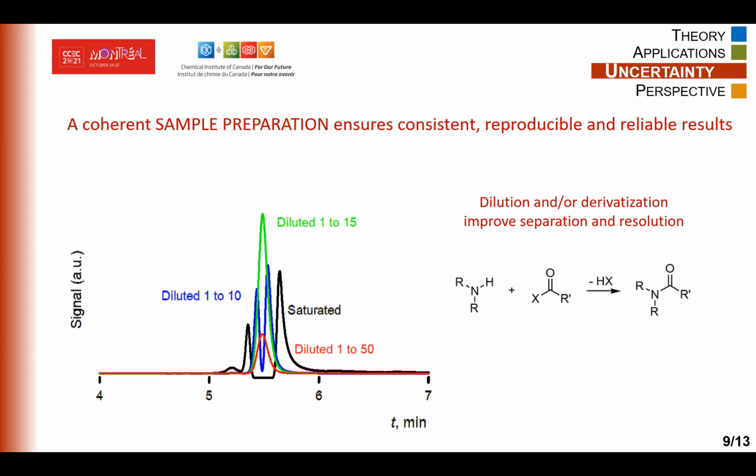They normally select the wrong filter. There are several membranes available, and they all have different applications. For example, in your lab, I'm sure you have cellulose acetate syringe filters, and they're very common, cheap, and used for aqueous solutions and biological samples. People use them on a daily basis, but they don't know that they dissolve at low pH and in several organic solvents. So if you work at these conditions, you might want to go with a polypropylene filter.